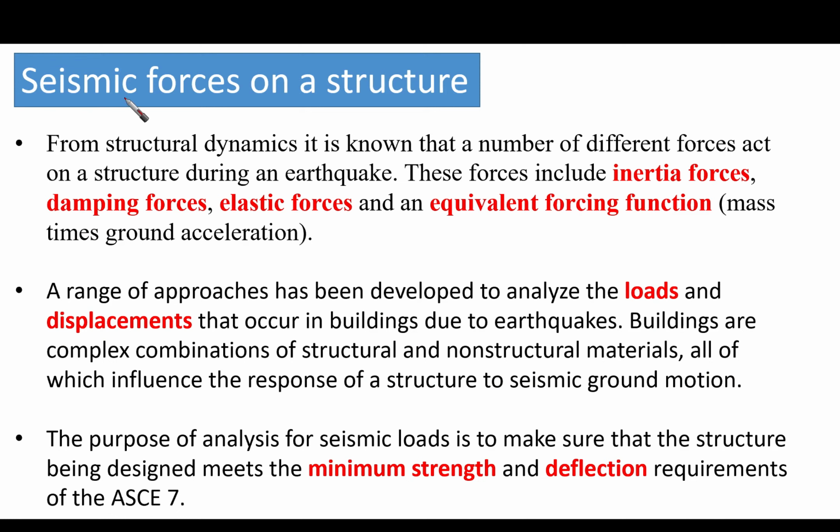Now let's talk about the seismic forces on a structure, and how ASCE is dealing with it. From structural dynamics, it is known that a number of different forces act on a structure during an earthquake. These forces include inertia forces, damping forces, elastic forces, and an equivalent forcing function. If you remember the equation of motion that I put before, I had one term for inertia plus another term for damping plus another term for elastic forces, and on the right hand side we put a term for the ground excitation, right?